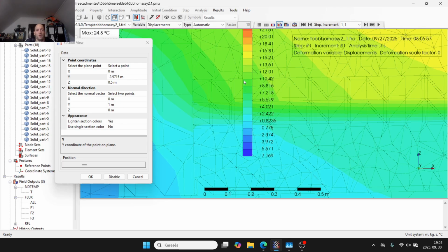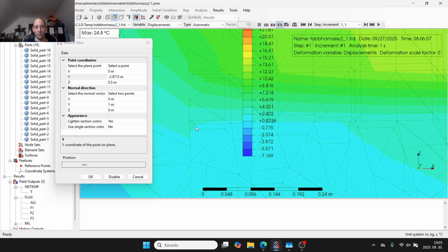vapor isolation well. Because vapor always finds the smallest hole to go to the place where it can condensate. So if here is some gap and no vapor isolation, vapor will come here and condensate there, and it can fill up your soil with water. And if there is any food for the molds, they will grow there.